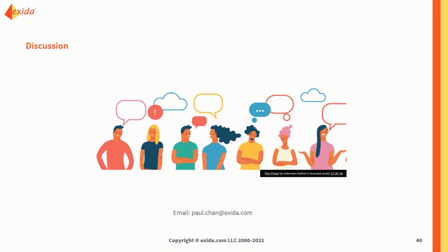So the other part of this question is, can we actually take a SIF as an IPL for another SIF? So this is something that, how to put this, within our consultancy expertise, there are different approaches towards this. For me, as long as the math works, it's fine. Because you need to make sure that, for example, there are two SIFs. One SIF is potentially being built as a SIL1 application.